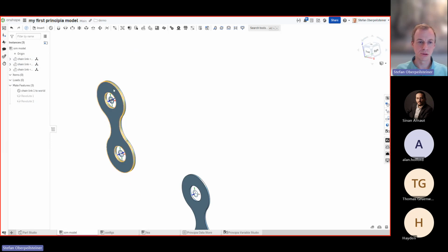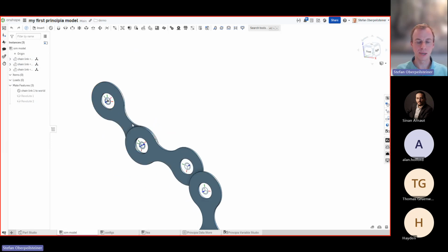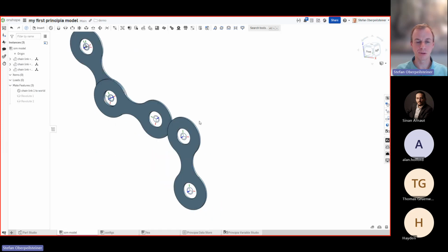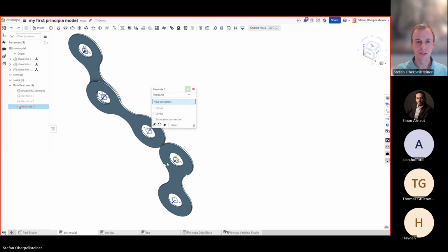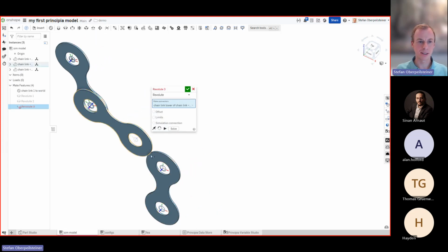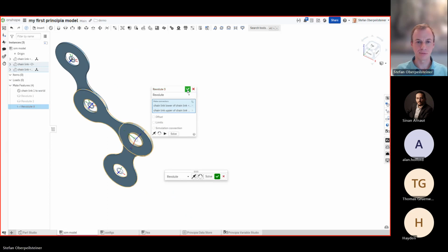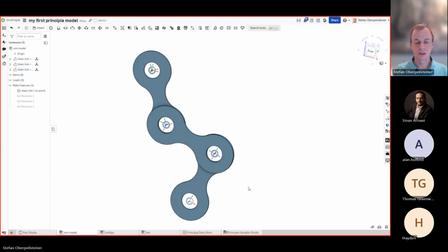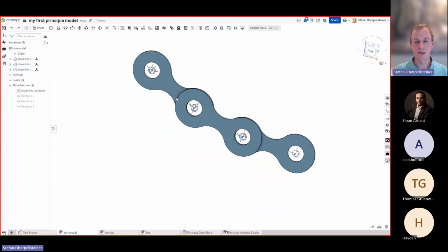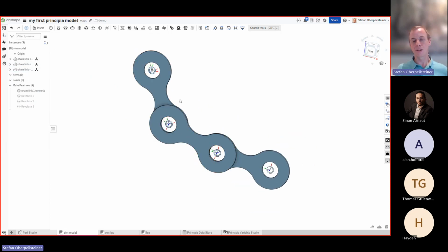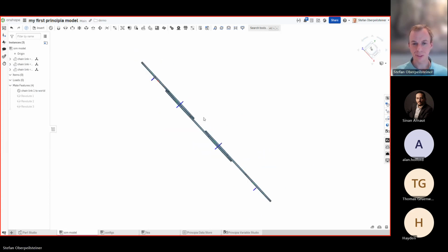And then in order to choose the right things, just use the kinematic solver of Onshape to create different configurations. And I add another Revolute joint here. So Revolute joint between the second and the third chain link. So I created a chain consisting out of the three links.